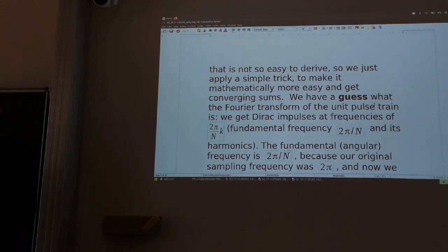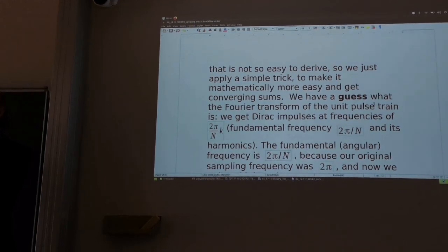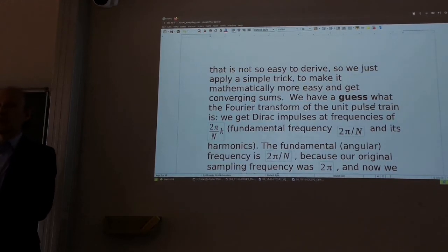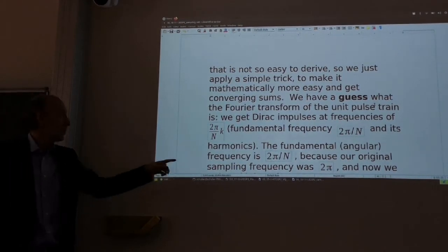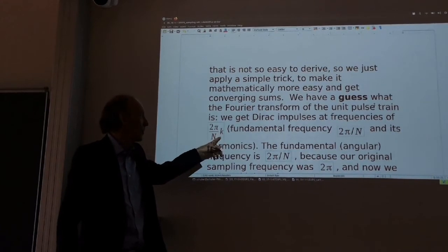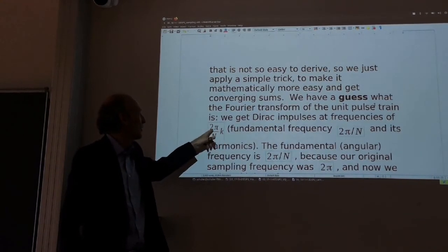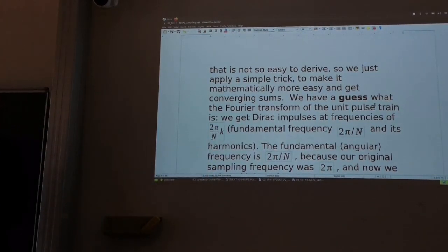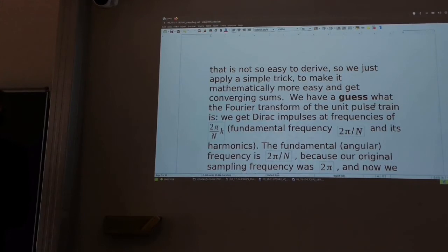It's not 0, because you only have positive pulses, but not negative ones. So you have DC. Makes sense? So that's why you also have to include k equals 0. So up to where will you go? What's the range of this index k? We know we start at 0. What's the upper end?